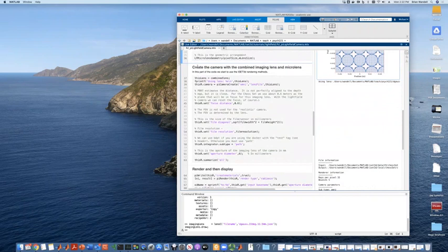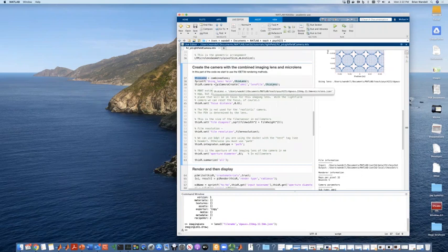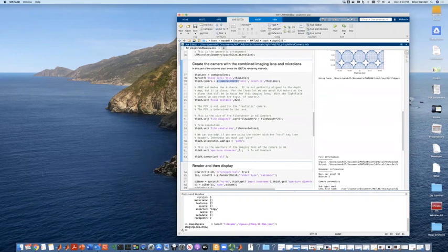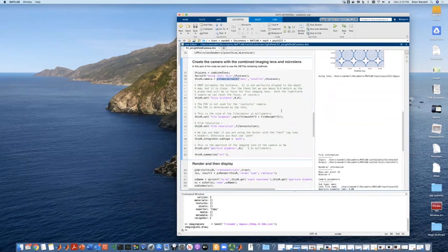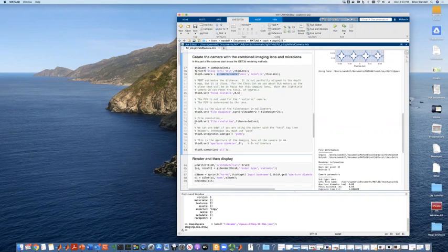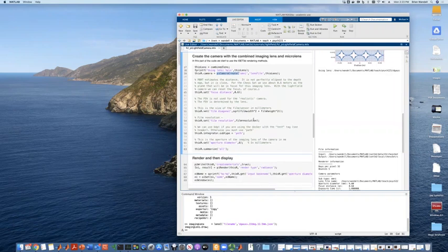And now this part here is the kind of coding that we use with this recipe in ISET3d. We built this combined lens and give it a name, and we print out a little information about it, and then we create a camera that has that lens. This is the way in ISET3d we create cameras. Pi for PBRT to ISET, pi camera create, and we're creating a particular type of camera. We're setting its focus distance. We're setting the size of the film or sensor that we're going to be simulating. We're telling you about the resolution, and so forth.